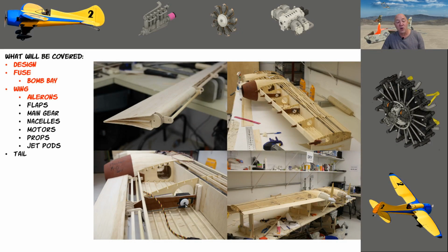Ailerons. On the upper left-hand corner, what you see on the front leading edge of that is a dowel rod. That would be replaced with a hard, like piano wire type thing to be the counterbalance. I try to counterbalance all of my flying surfaces. If you look at real aircraft, they're normally balanced. That's the reason they don't flutter. So if you don't know about that, reach out to me. I'm actually going to make a video on flying surfaces. It's just on my list.